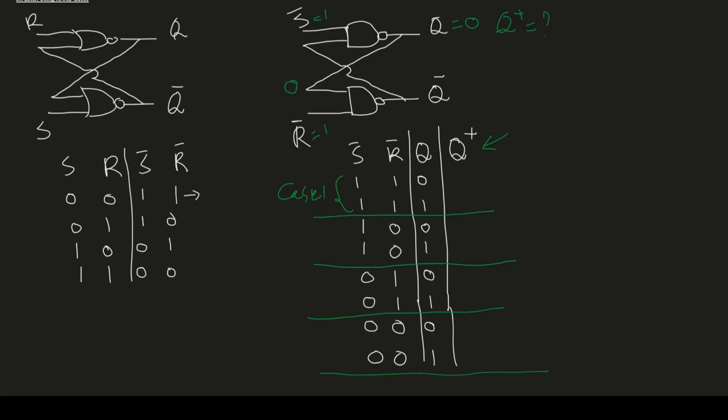We can also write the table of the NAND gate, the truth table of the NAND gate. We have two inputs, I1 and I2, and the output O. The inputs are 0 0, 0 1, 1 0, and 1 1. For the AND gate, the output is 1 when both inputs are 1, but the NAND gate is the opposite. So for 1 1, we get 0, and the rest are 1s.